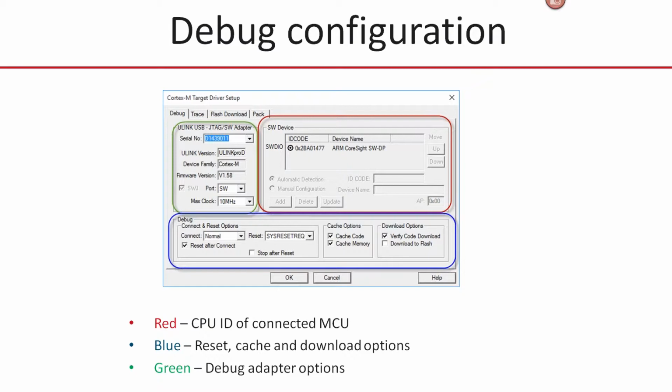So this is a good way to know if you've got a running processor when you're first bringing up hardware. Just plug in the JTAG, open this debug window, and you know if the device is working. If there's nothing in this box, then you have a fundamental problem with the clock crystal or power or something similar.